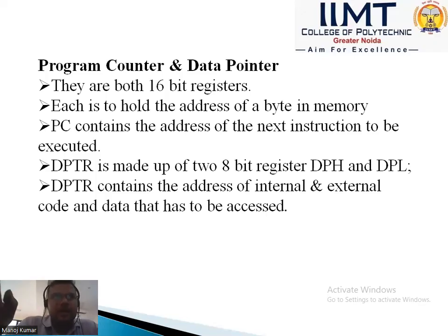This is the program counter and data pointer. They are 16-bit registers, so two 8-bit registers are required. One register contains 8-bit data. Each holds the address of a byte in memory. PC contains the address of the next instruction to execute.